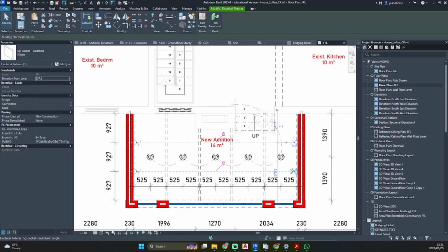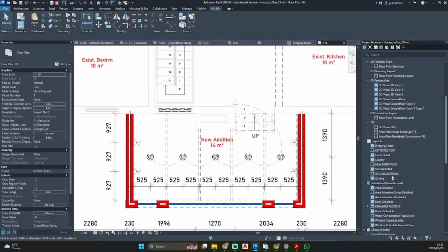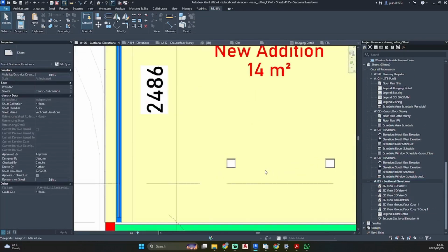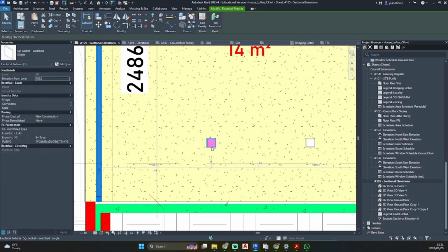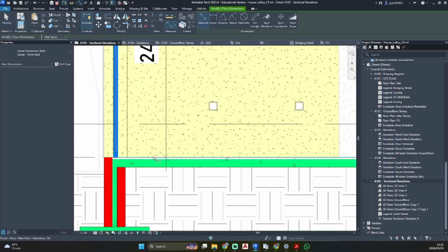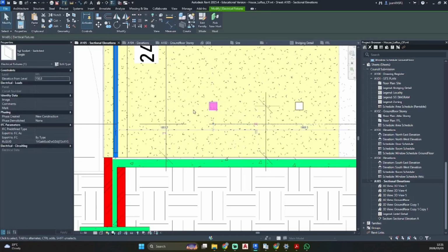in with our wall plugs. So I'm just gonna select my sockets and change this height to 150. If we go to a section, there is our wall plug. So I like to do my wall plugs nice and high. So let's make this an equal 550.